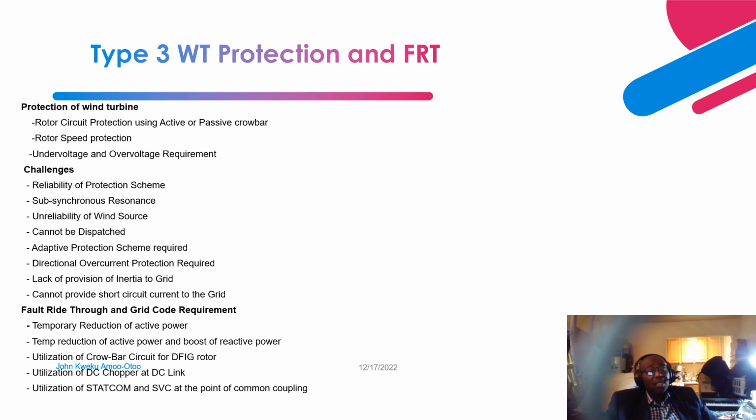capacitors to increase the amount of power that is being transmitted. If you install a series capacitor, what does it do? It decreases the reactance of the transmission line. So XL minus XC is the bottom part of the power curve. Power is equal to V1 V2 sine delta over X.